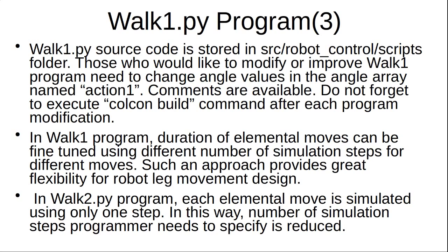walk1.py source code is stored in src robot_control scripts folder. Those who would like to modify or improve walk1 program need to change angle values in the angle array named action1. Comments are available. Do not forget to execute colcon build command after each program modification. In walk1 program, duration of elemental moves can be fine-tuned using different number of simulation steps for different moves. Such an approach provides great flexibility for robot-like movement design.